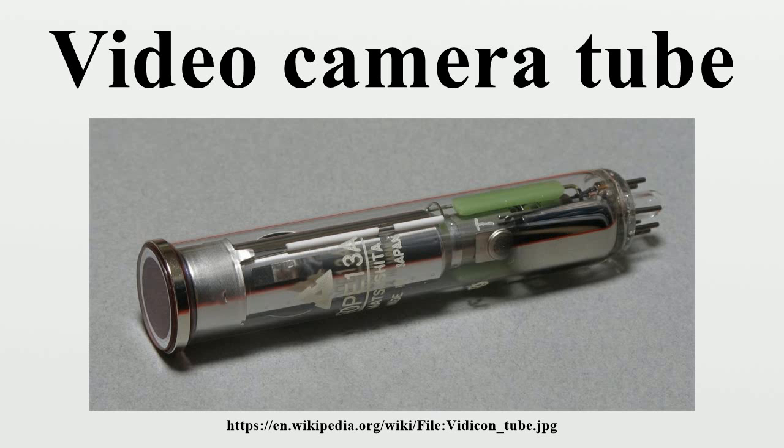These experiments were conducted before March 1914, when Minchin died, but they were later repeated by two different teams in 1937, by H. Miller and J. W. Strange from EMI, and by H. Iams and A. Rose from RCA. Both teams succeeded in transmitting very faint images with the original Campbell-Swinton's selenium-coated plate, but much better images were obtained when the metal plate was covered with zinc sulfide or selenide, or with aluminum or zirconium oxide treated with cesium. These experiments are the base of the future vidicon.